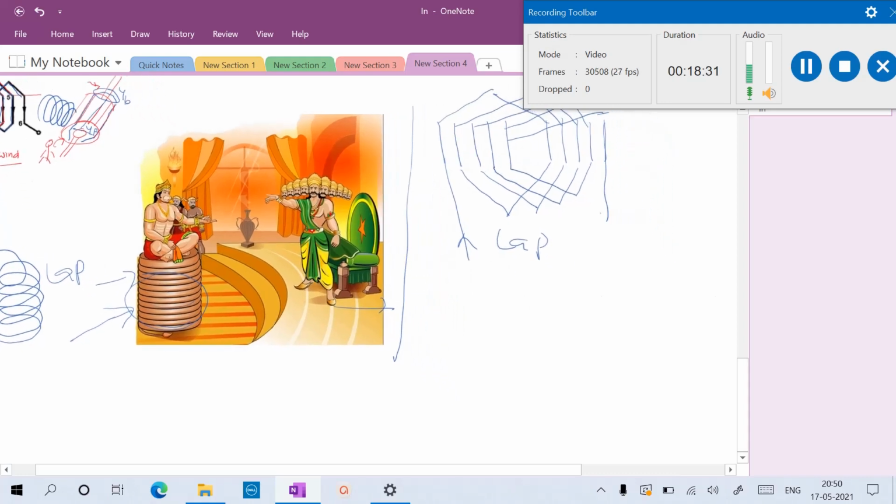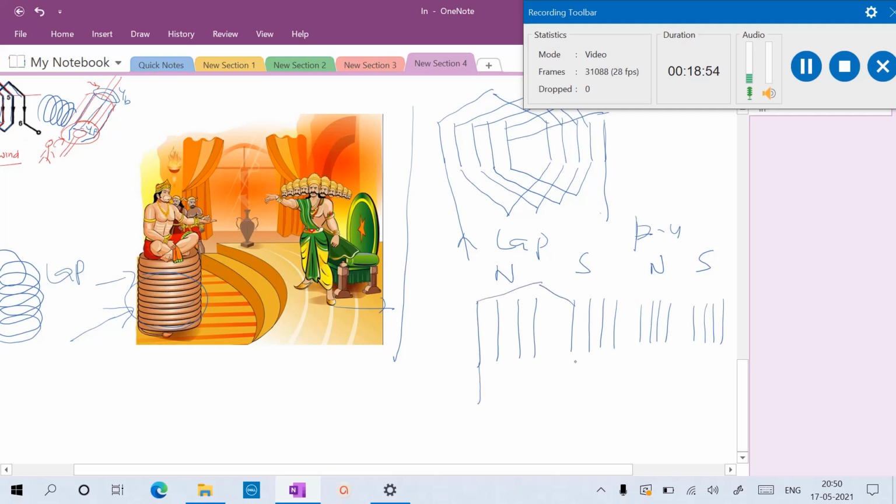Coming to the wave winding, what is a wave winding? For example, 1, 2, 3, 4, under the influence of North Pole, South Pole, North Pole, South Pole, for a 4-pole machine, P is equal to 4. Now this is a conductor. The first one is connected to one pole pitch in the south. Next, instead of coming back, it goes to another pole pitch, and then another. That means it is going in a wave.